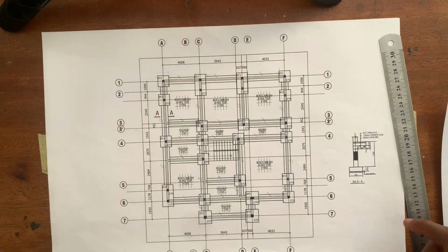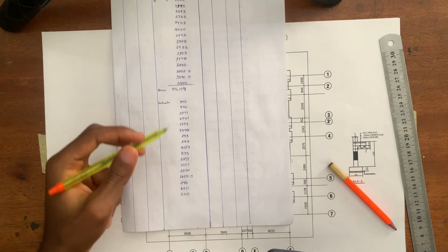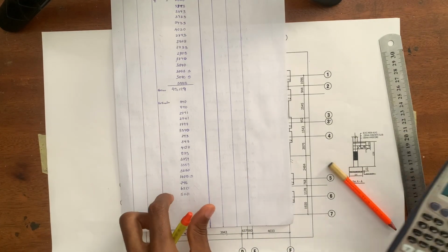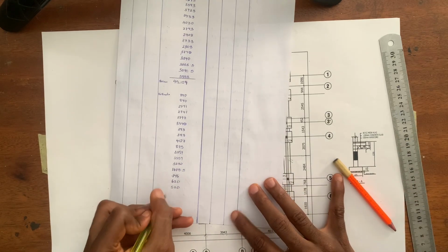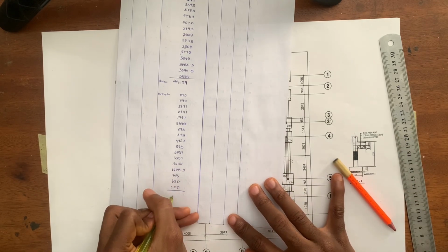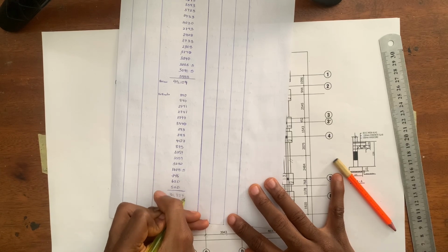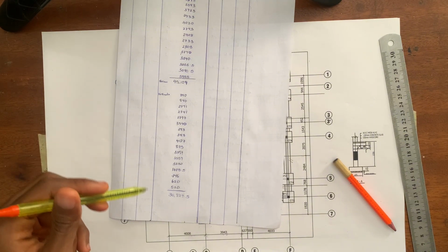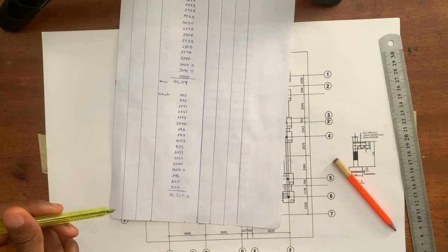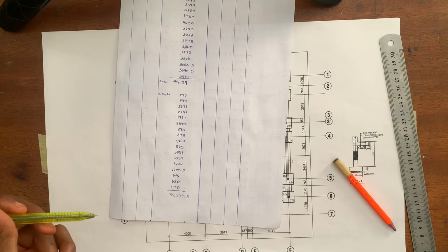So doing that, we've measured all the vertical trenches in this drawing. All we just need to do now is get the summation of everything. So if you add all the verticals together, we're going to have 30,829.5. So we'll now record it. 30,829.5. So with these, we've measured the center line for our foundation trench excavation.